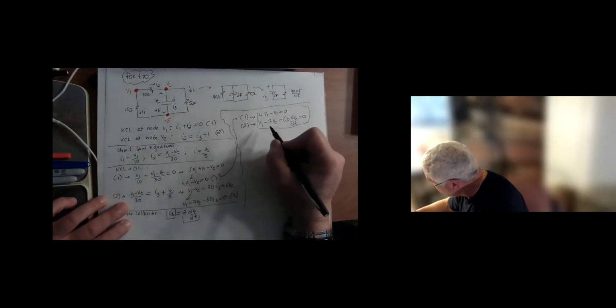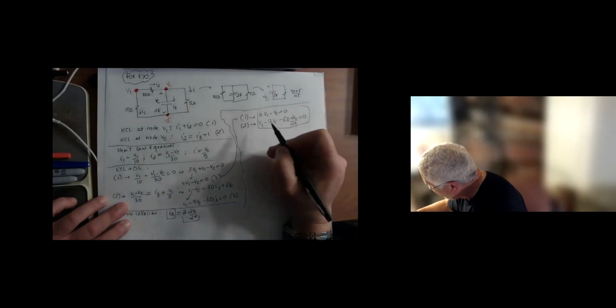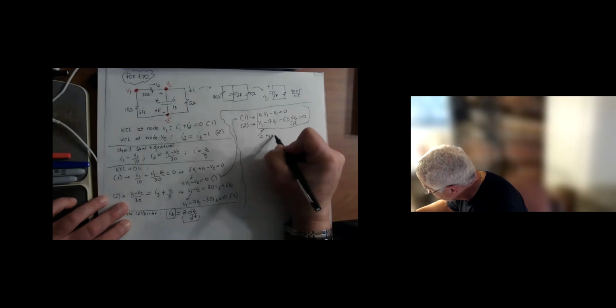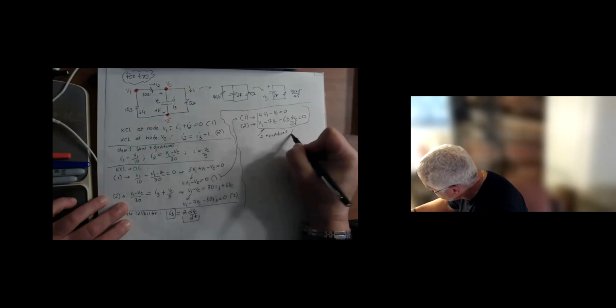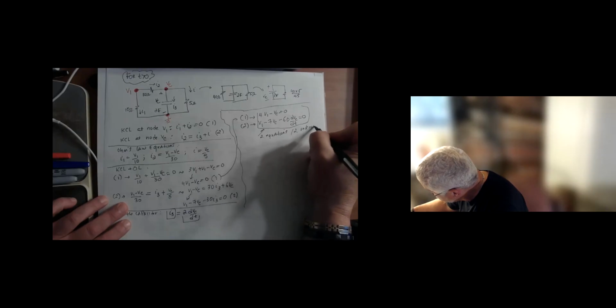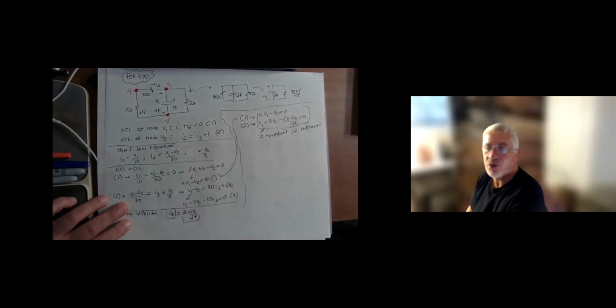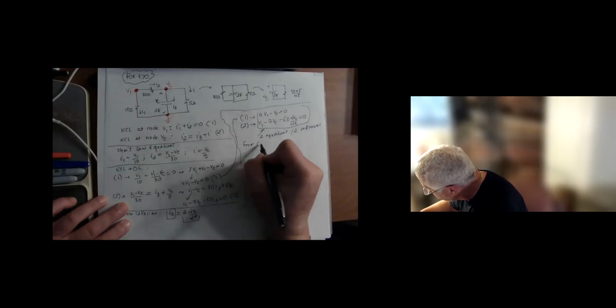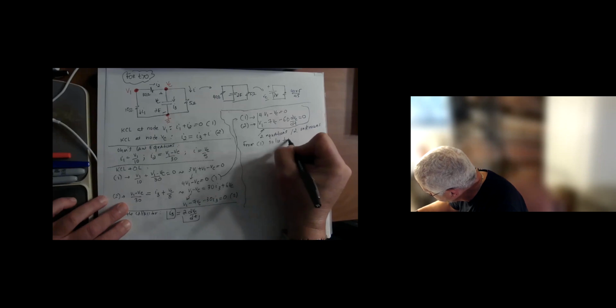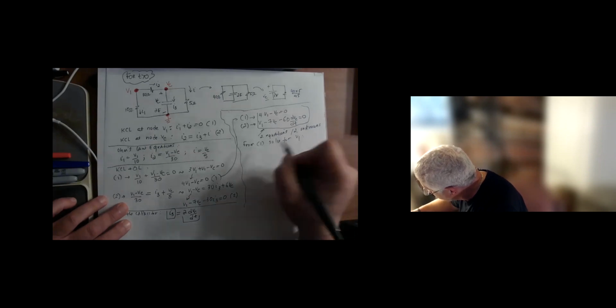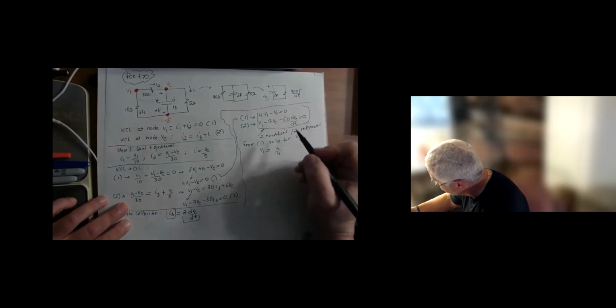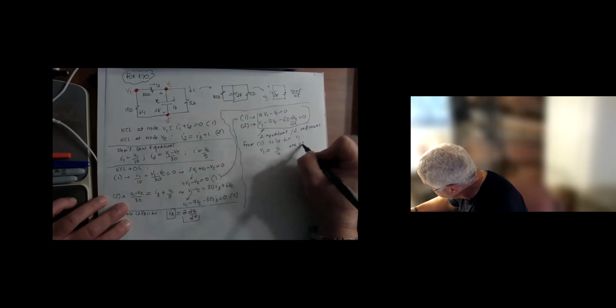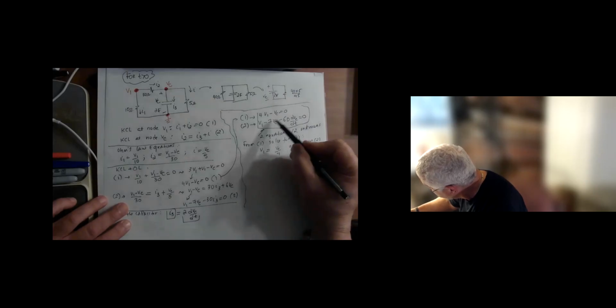All right. At this point, I want you to look at how many equations you have. I have 2 equations and how many unknowns? I have 2 equations, 2 unknowns. So what do we do when we have 2 equations, 2 unknowns? I can solve from 1. I can solve for V1. Okay. So V1 is equal to what? VC over 4.